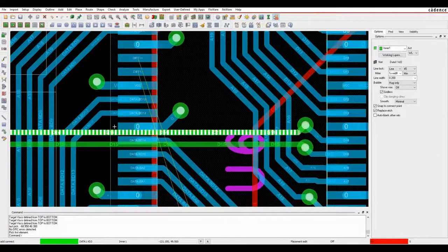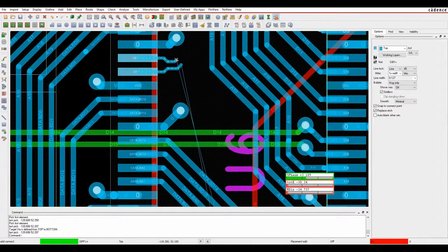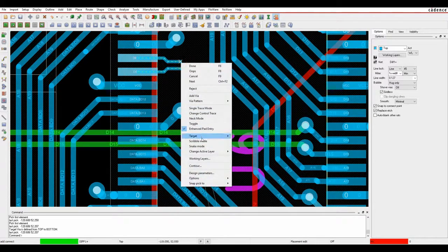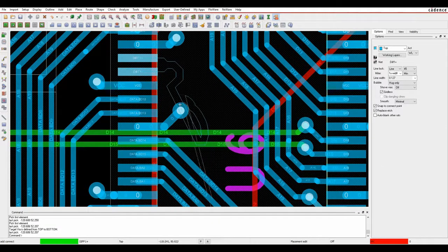I now want to route a differential pair, so if I individually select a single connection of one of the pins, the pair jumps together based on the rules from Constraint Manager for differential pairs. I'm also getting some heads-up display for phase tolerance, total edge length and relative propagation delay, and these values will update as I start to route. I can also use a command here called right-click scribble, which actually allows me to just guide my mouse where I want it to go. As soon as I make a left click, that routing is then confirmed.